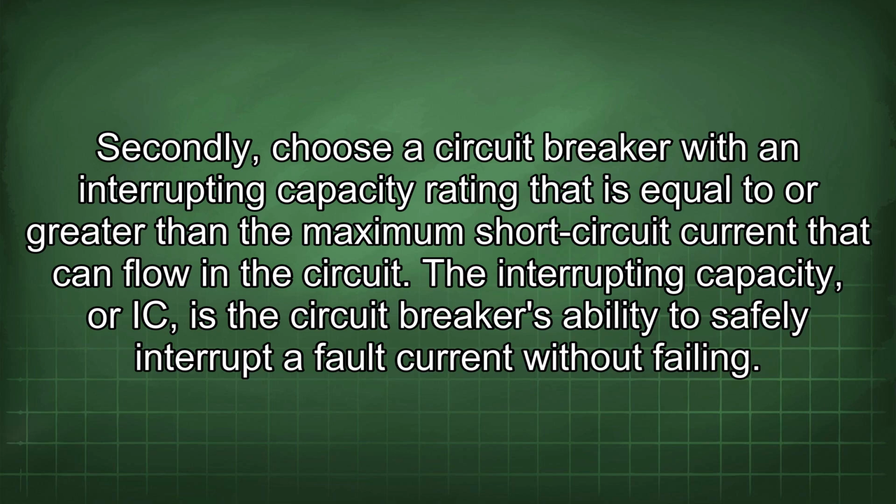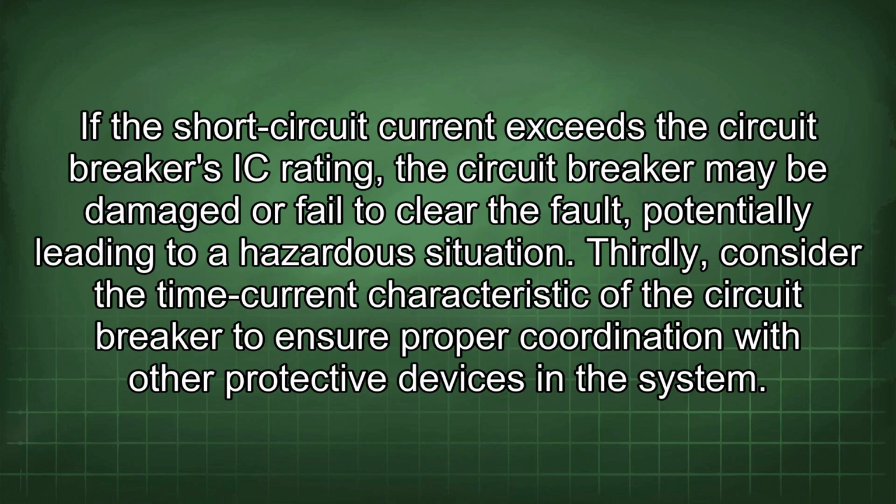The interrupting capacity, or IC, is the circuit breaker's ability to safely interrupt a fault current without failing. If the short-circuit current exceeds the circuit breaker's IC rating, the circuit breaker may be damaged or fail to clear the fault, potentially leading to a hazardous situation.